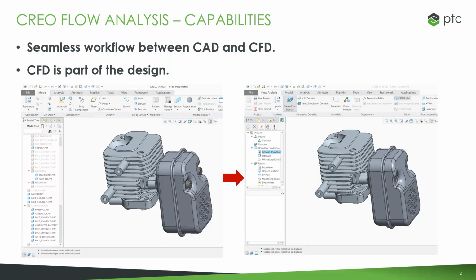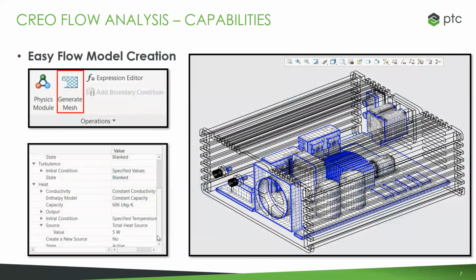We've broken down the barrier between those two different worlds, between design and analysis, and are working more within one unified analysis-driven design environment. And as you'll see, whenever I go through and build these simulation studies out, the flow model creation is very straightforward. For example, you have the ability to tell the system to automatically generate the mesh for the analysis. You, the user, don't have to go through and define all that yourself. You still have the ability to have more manual control over the process in areas that you might like to. But if it's easy and it's something that you want built out for you, that's right there, done for you.